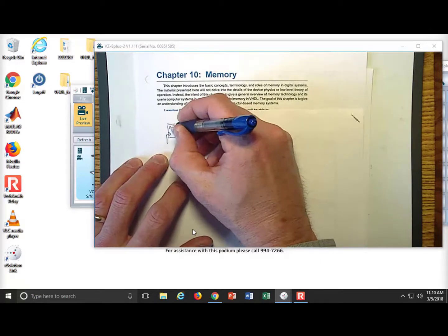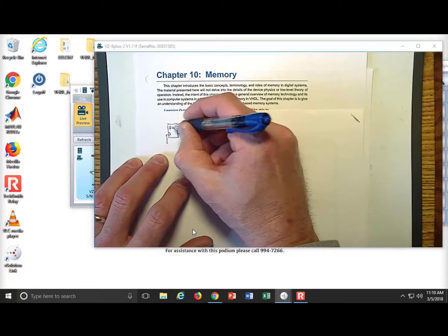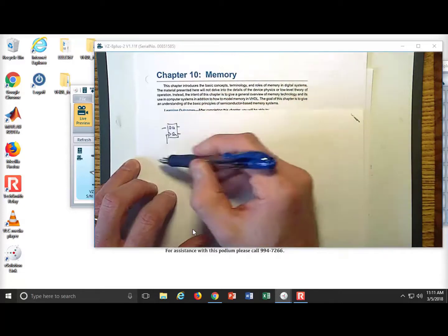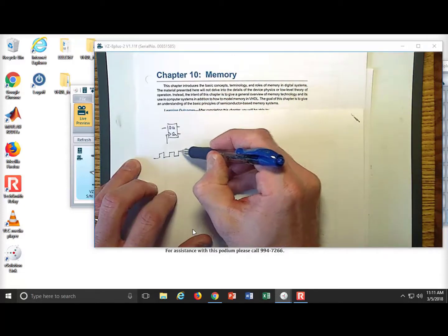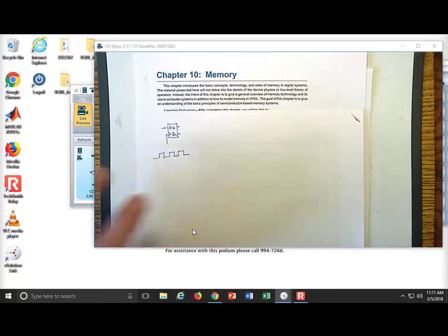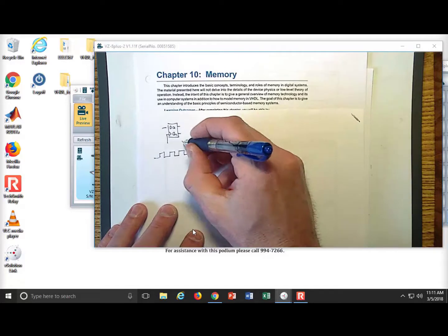This absolutely can store information. It's very synchronous, meaning that a clock comes into the system, and we grab information on every rising edge of a clock, and we store it. So Q will hold D. That is storage, okay?